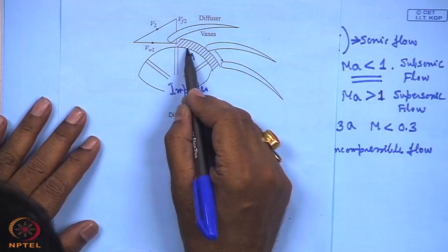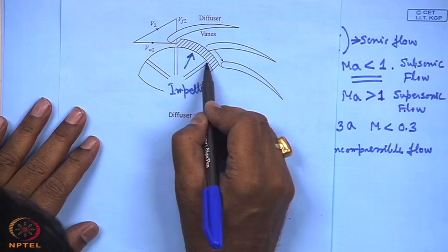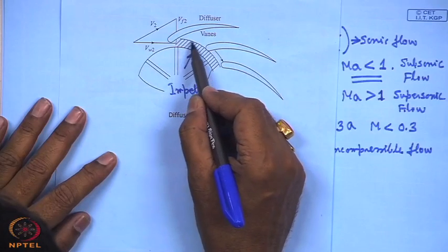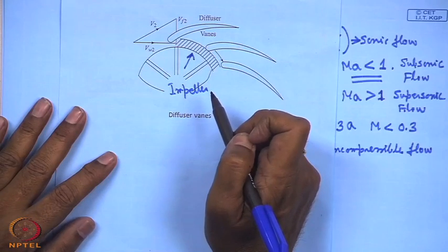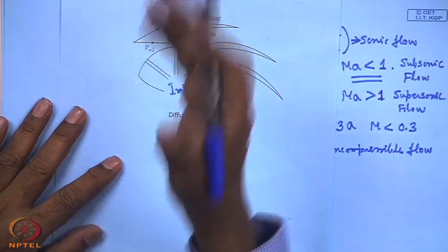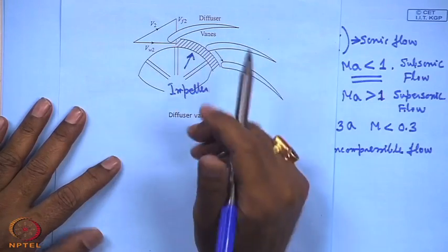Kinetic energy will be there as required to maintain the flow. So, therefore, what happens? The excess kinetic energy, which is undesirable, is then converted to pressure energy, or converted to higher static pressure, in the diffuser. The similar thing which is done in the case of centrifugal pump.